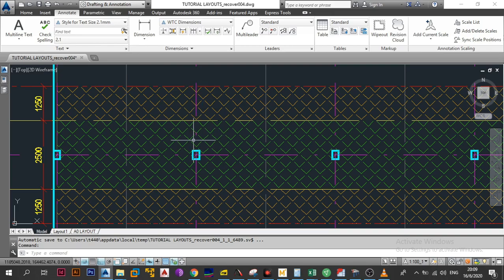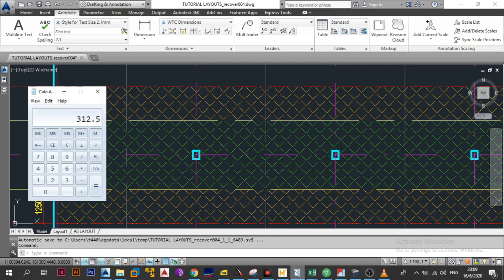So what they're saying is you're going to divide it: 75% of the 250 at this point in the column strip. So let's just put a calculator. The value is 75% multiplied by 250, so 0.75 multiplied by 250. This will give you 187.5.